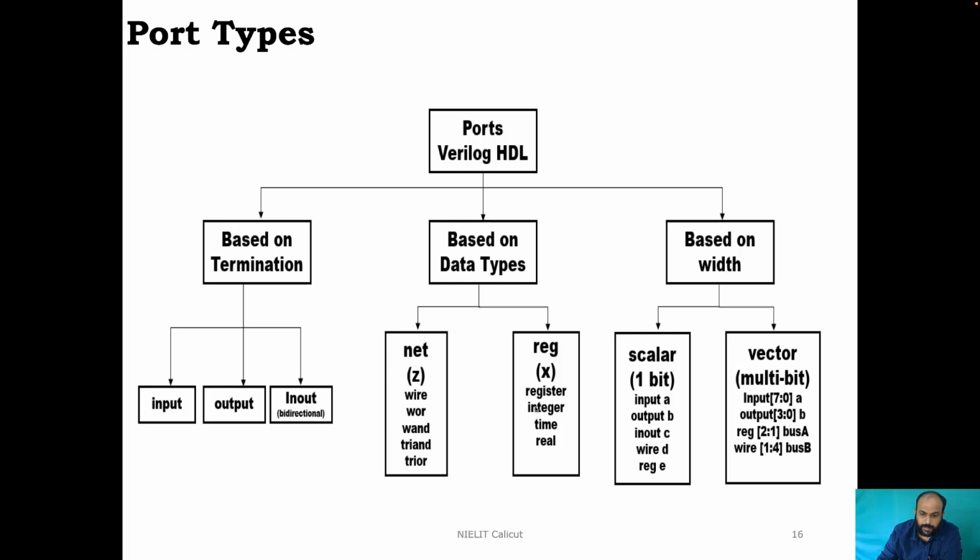Reg is the keyword, and the other keywords are integer, time, real, and so on. You also should remember what is the default value in each of these data types. The default value of net is high impedance, or Z, and the default value of register data type is X.